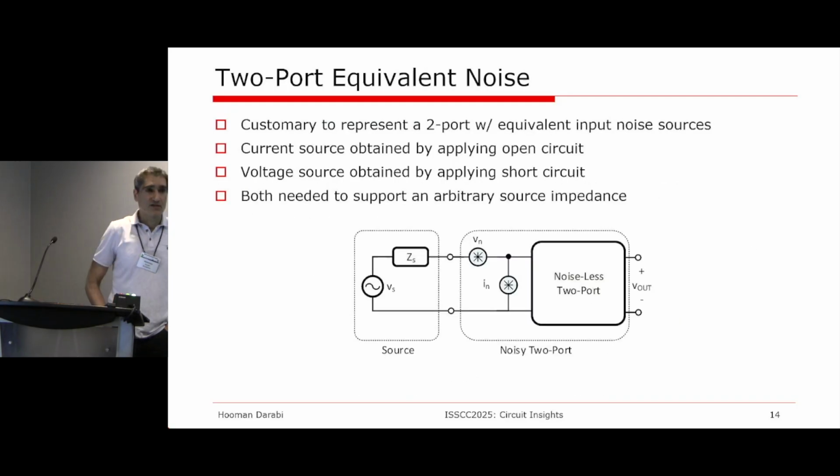If you have a complicated circuit consisting of many transistors and whatnot, and resistors, it is foreseeable that you can lump or model all the noise sources as one equivalent voltage noise source and one equivalent current noise source. I'm using these funny shapes, the plus minuses or arrows for voltage or current source, not shown because it's not important. For noise, it's always squared when you do the power spectral density. So -1 versus +1 doesn't make any material difference.